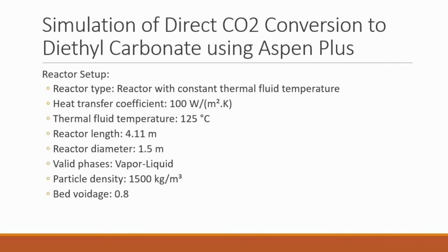Reactor length: 4.11 meter. Reactor diameter: 1.5 meter. These dimensions determine the reactor's volume. Valid phases: vapor-liquid. Particle density: 1,500 kilograms per meter cubed. Bed voidage: 0.8.